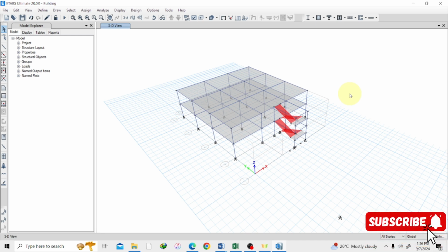Because with these divisions, the Etabs software is going to run the analysis by these divisions. So you can either choose to divide your slab into smaller sections or larger sections, because it's going to analyze each individual section that you've created. There are advantages and disadvantages of making them smaller and also making them bigger.